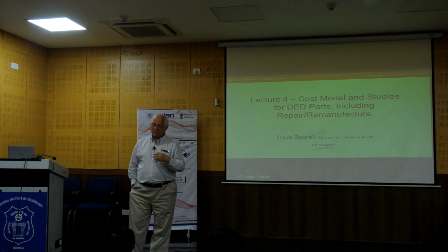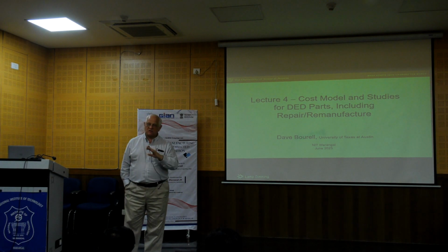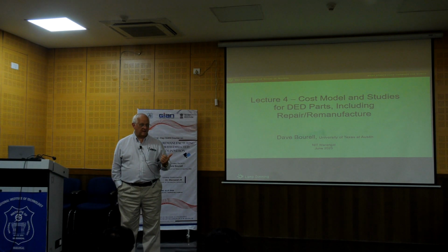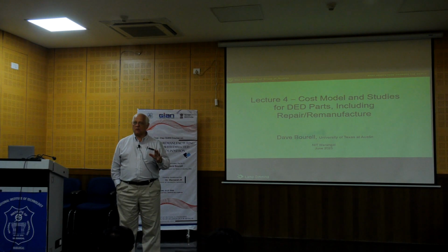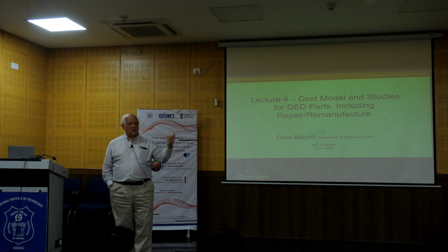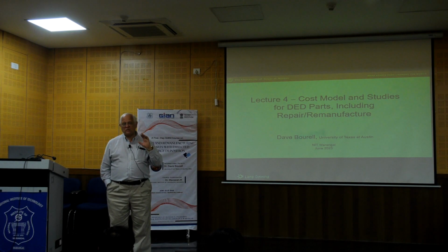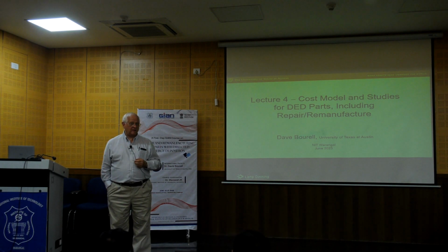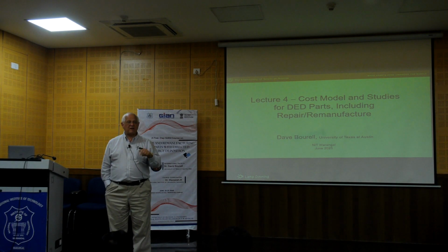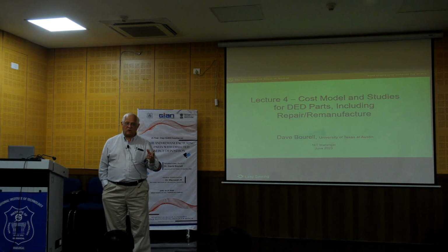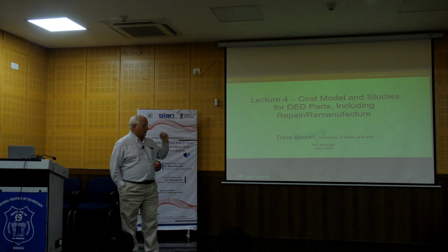So, for example, I can tell you just immediately with nylon and powder bed fusion, which is sort of my long suit, that the cost of the powder is almost negligible, has a negligible effect on the cost of the part. The place where we save money on the cost of the part in polymer powder bed is by making the machine cheaper that fabricates the part, or by making more parts in a given period of time, that is, to increase the production rate. And that's where all the effort is. It's all based on understanding the cost models.